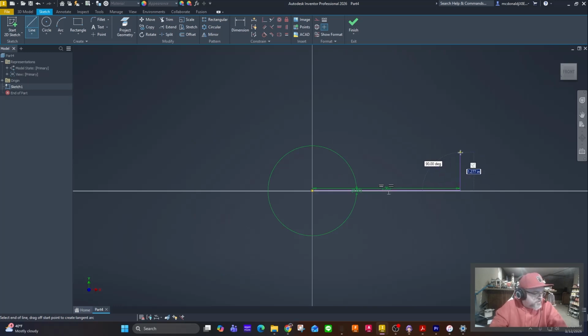Now we're going to go straight up to form the next part of our drawing. Whenever you have a shape like this that has different fillets and chamfers, the way I work this is I create the overall block that's the boundaries of the piece, as if you were handing a machinist a full block of metal and then having them whittle away or cut different angles and parts off to get that final shape.